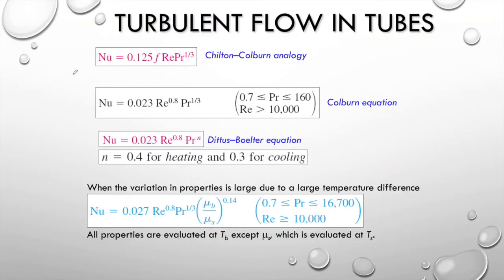And then what if this question falls under turbulent flow? We calculate the Reynolds number, and the Reynolds number is around 15,000, for example. So we have to assume fully turbulent flow. So do we have a friction factor? This is out of our method. We are not using the friction factor in order to solve for the Nusselt number. So let's focus on this.